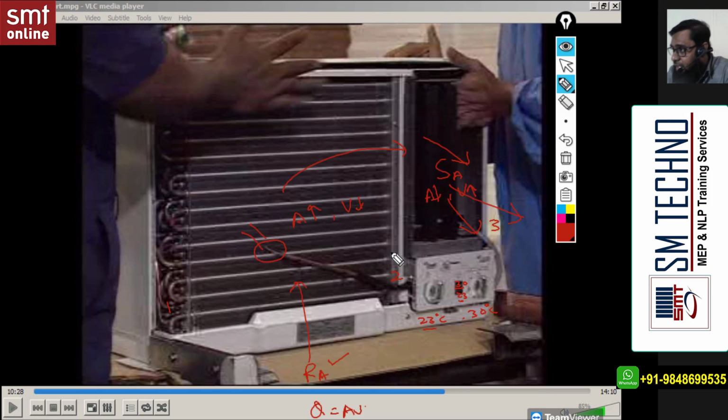After some time, if the load increases, if the temperature increases, because it is monitoring continuously, suppose after some time the temperature is now say 24 or 25, quickly with the sensor the compressor will switch on. Like this the machine controls. And remember, this controlling is not only for window AC, this controlling is for all air conditioning systems. Okay, in split, in ducted split, package, even in chilled water AHUs. What AHUs are we'll discuss. So remember, the return temperature is responsible for controlling the room temperature. But in a chilled water system, we'll talk about the return water controlling the chiller.